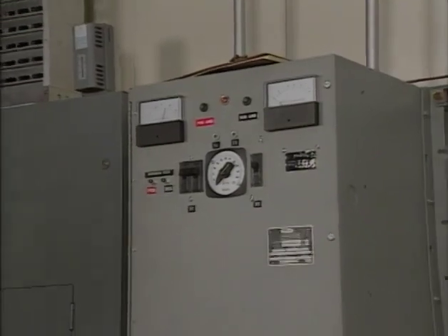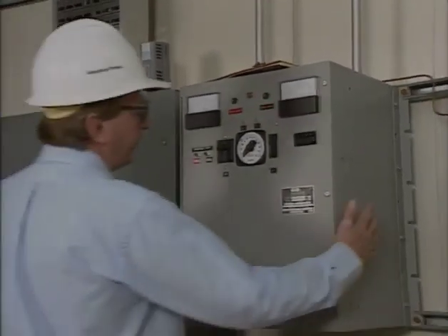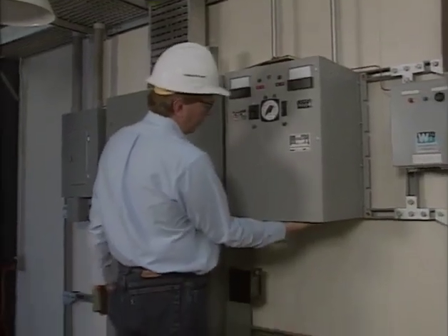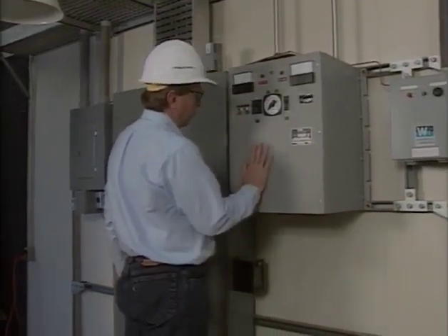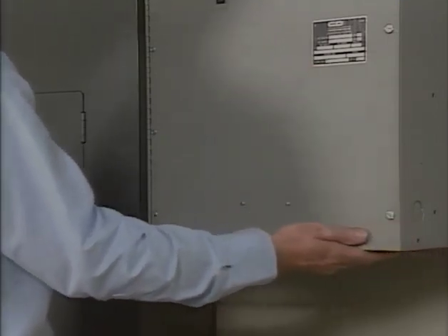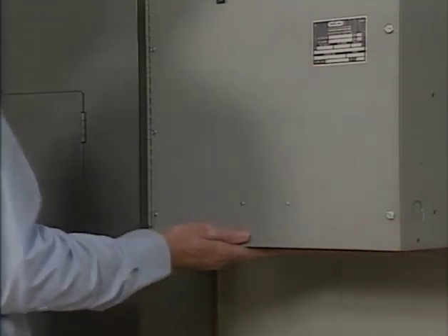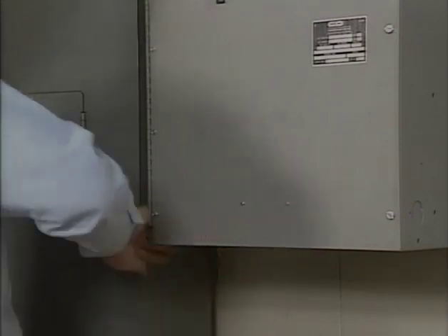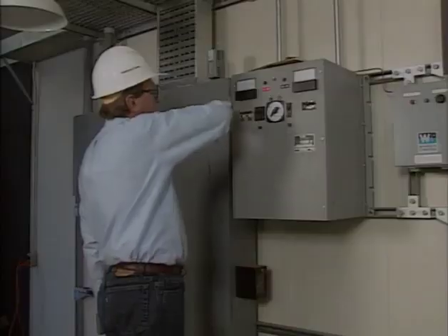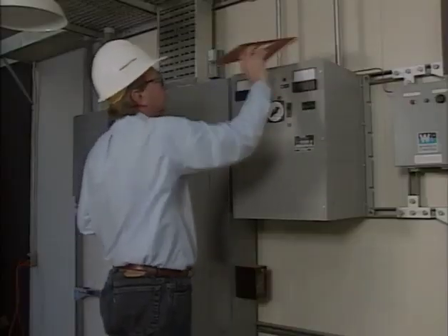In general, charger inspection and adjustment steps can be done in any sequence. A good place to begin is to check the charger for signs of excessive heat. The outside of the charger can be felt to determine if the charger is too hot. Excessive heat may indicate faulty internal components, poor internal connections, or poor ventilation. Excessive heat can result in charger failure.